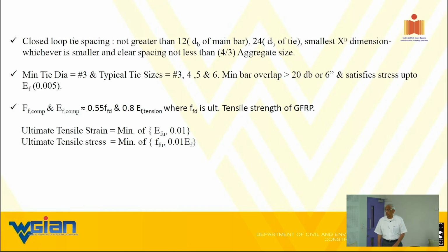No, we first used sandpaper to clean that place, and we have a Fevikwik kind of glue. So we just paste the gauge on that portion, so that the wire will come out. Yeah, well, you can do that. But now we are getting wireless gauges. You can put it there and it will send a signal. You will get an answer. That's much easier. When I was a student, I put all these gauges; we didn't have the wireless gauge at that time. So we used to put about 20 gauges on a sample, to understand the whole crack profile, not just one location. Profile also you can get.